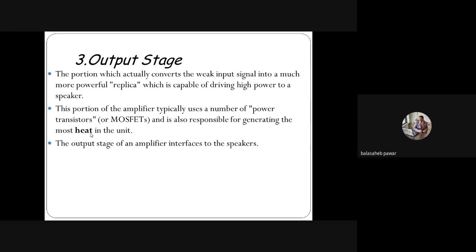Okay. Yesterday again I told that speaker resistance is mostly 4 to just 8 ohms. And that's why it works as good as short circuited. Not short circuited, but as good as short circuited. Why am I saying as good as short circuited? Because as the resistance is very low, the amount of current flowing through that load, or the current consumed by that load, is very high. And hence that last stage, that is our amplifier stage, takes the care. That means not only voltage amplification, the care taken by this last stage is about power amplification. That means overall power gets improved.